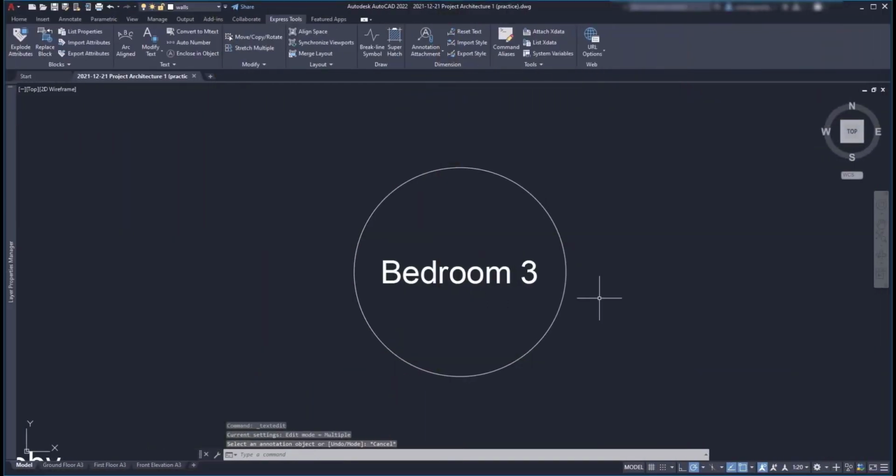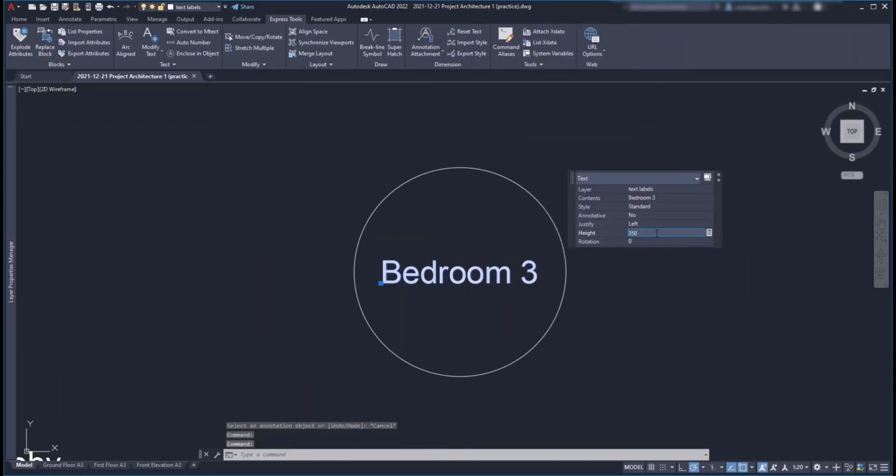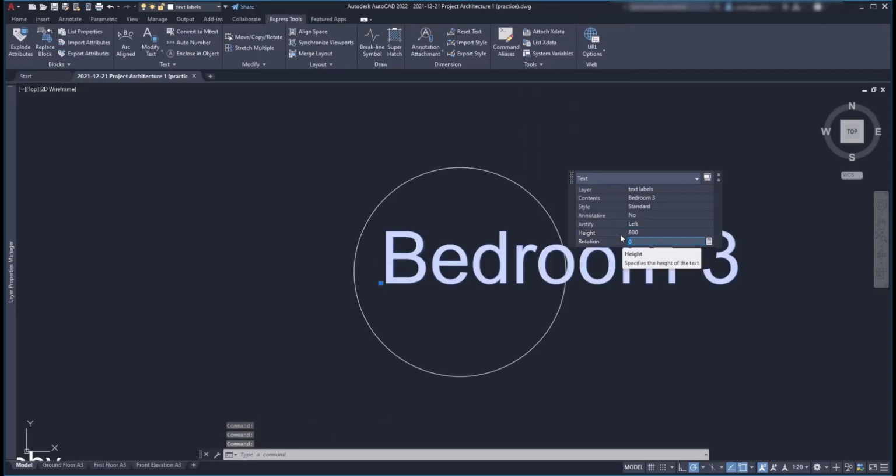One last thing, the text and object keep their independence, in the sense that in this situation the circle is not following the text if I change the text size. This was something I didn't understand when I was exploring this command, what variable and constant meant. I thought when we changed the text height or the text itself, the object would adapt to the new size, but it didn't. Actually, variable and constant only work for a multiple text selection.